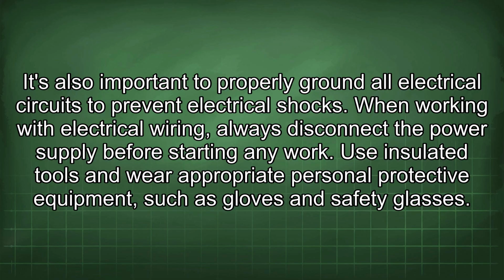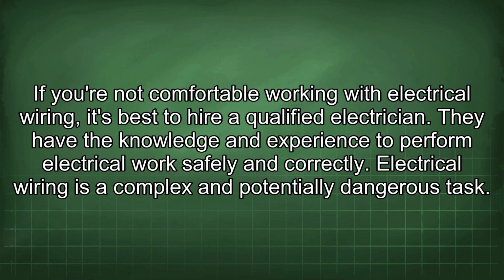When working with electrical wiring, always disconnect the power supply before starting any work. Use insulated tools and wear appropriate personal protective equipment, such as gloves and safety glasses. If you're not comfortable working with electrical wiring, it's best to hire a qualified electrician. They have the knowledge and experience to perform electrical work safely and correctly. Electrical wiring is a complex and potentially dangerous task.